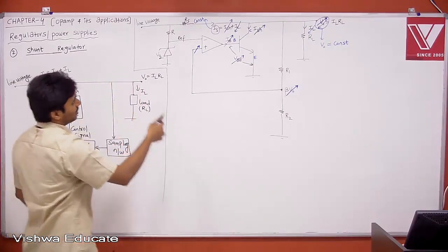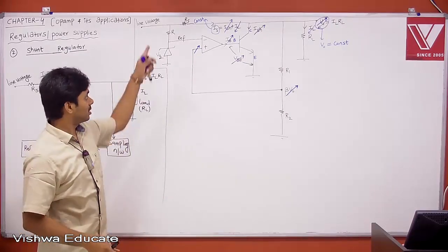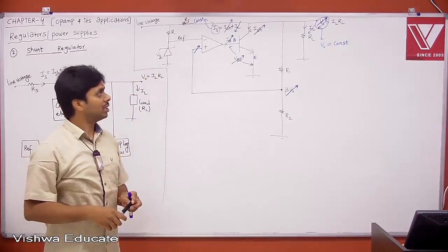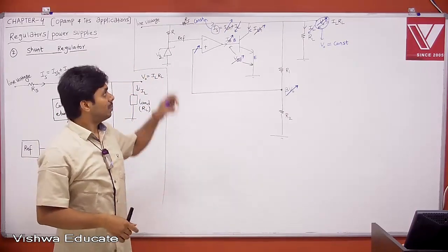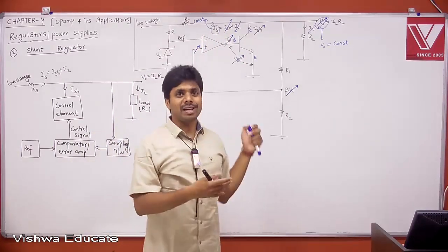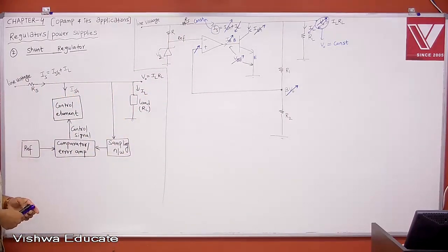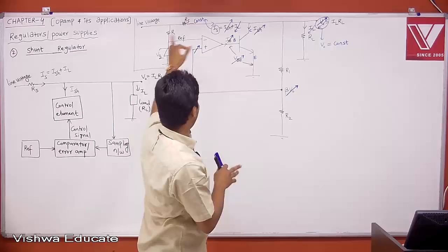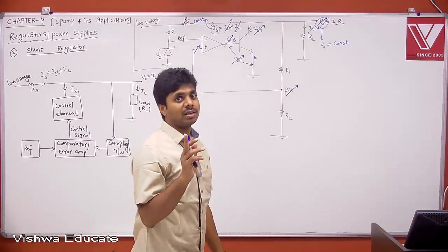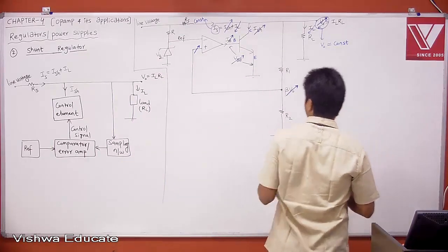See the small correction making the circuit a regulator, else it is not a regulator. The series resistor is important, because earlier, in the case of a series regulator, we didn't need a series resistor, because the BJT was a control element in series from input to output, and that would control. But now here we need a series resistor. Okay, that's fine. Now whatever I explained is valid, provided your line voltage is not directly shorted to your output voltage. Very important, right? That is theoretical knowledge versus practical knowledge. Theoretically, even though it is convincing, practically it may not work.